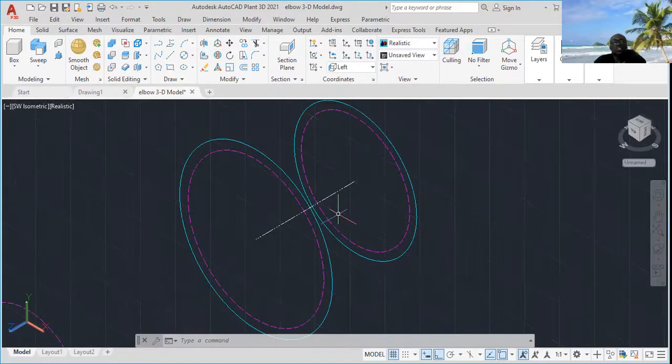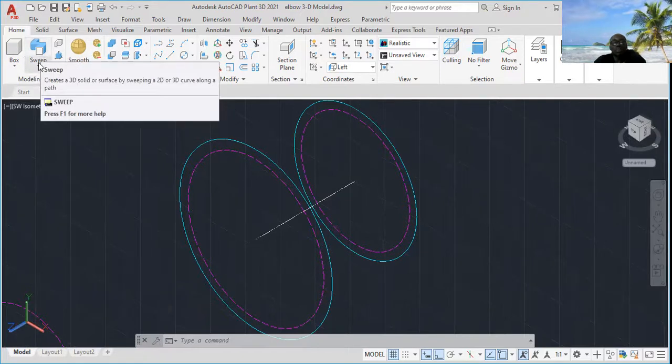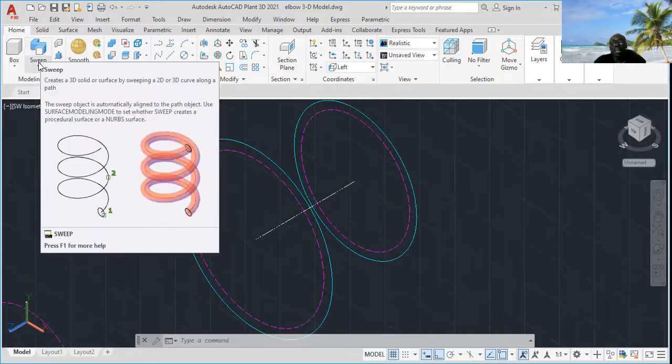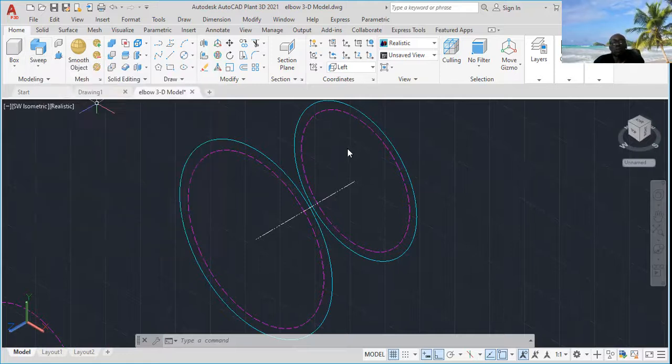What I'm going to do is, I'm going to come here to the modeling section in the ribbon. The first part is the modeling section. So what I have there currently is sweep. Yours will likely be extrude. So I've already used that, is why it's on sweep. Okay, I used it not long ago. So I'm looking for the only thing that can convert this thing to a 3D model, a command called loft. Sweep command will not be able to convert it. Extrude command can do it.